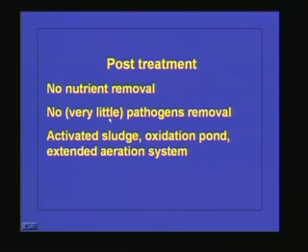So usually after the anaerobic treatment process, we give post treatment, and most of the time the post treatment is either an activated sludge unit, an oxidation pond, a maturation pond or an extended aeration system, because we know that all the minerals or inorganic substances present in the wastewater will be in the reduced condition when they come out of the anaerobic reactor, because in the anaerobic reactor a complete anaerobic condition, an environment conducive for reduction, is existing. So whatever is there, it will be coming out in the completely reduced form.